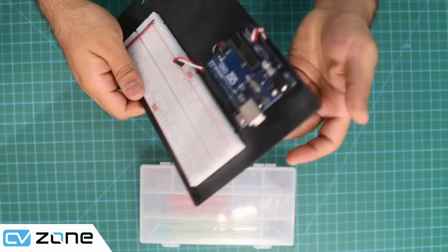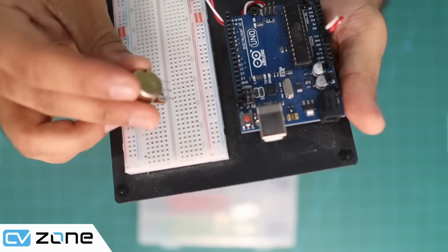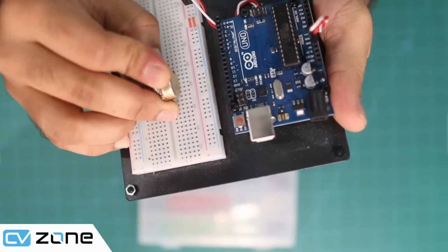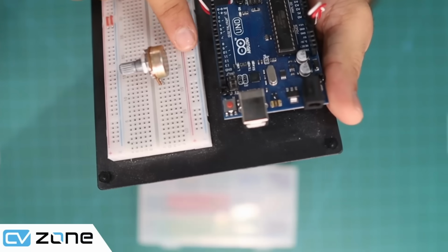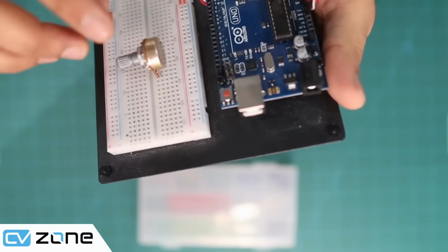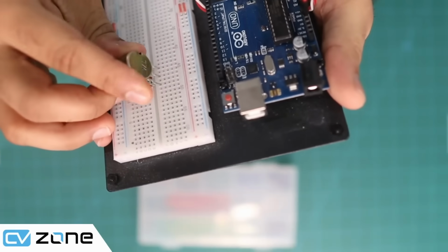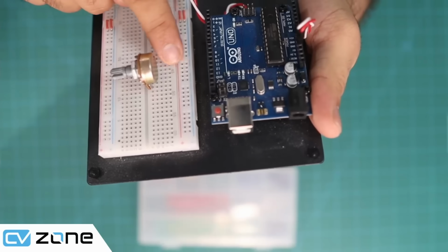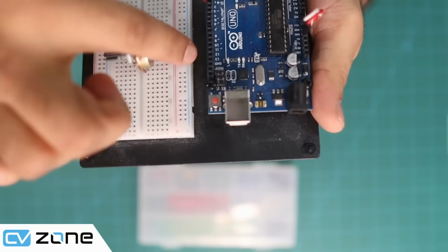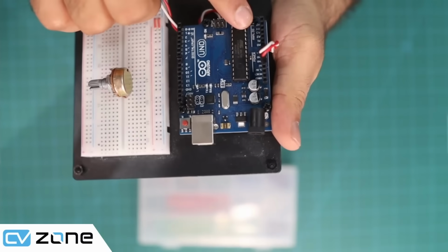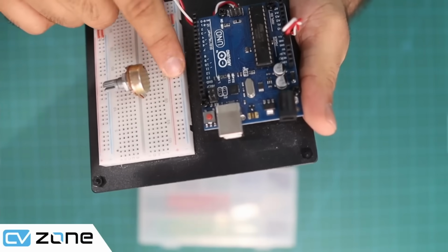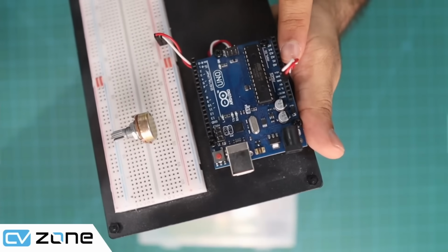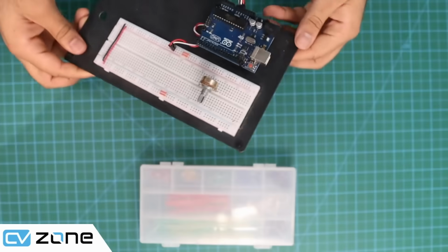So here, how are we going to attach this? We are going to simply place it here, let's say over here, and now we are going to attach our positive and negative cables. We can put it at the end and attach it to the positive and negative, because this line is positive and negative, so we don't need to go to our Arduino board to connect it. We can simply connect it here, and the signal pin we will bring up from here and connect to A0 over here. So let's go ahead and do that.